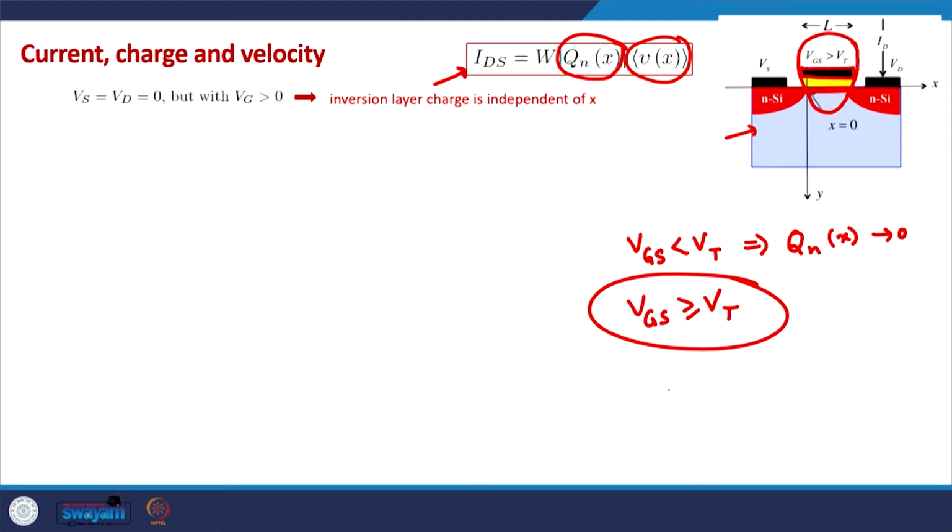So, if the capacitance of this capacitor is Cg, the gate capacitance of the MOSFET, which is approximately equal to Cox in most of the cases. While we do not want to deal with the details of the capacitance in the MOSFET, we generally take Cg to be equal to Cox, but ideally Cg includes Cox and the depletion capacitance of the channel.